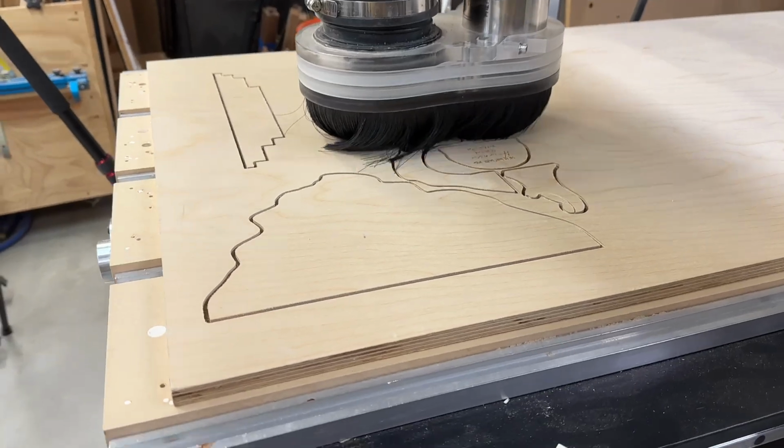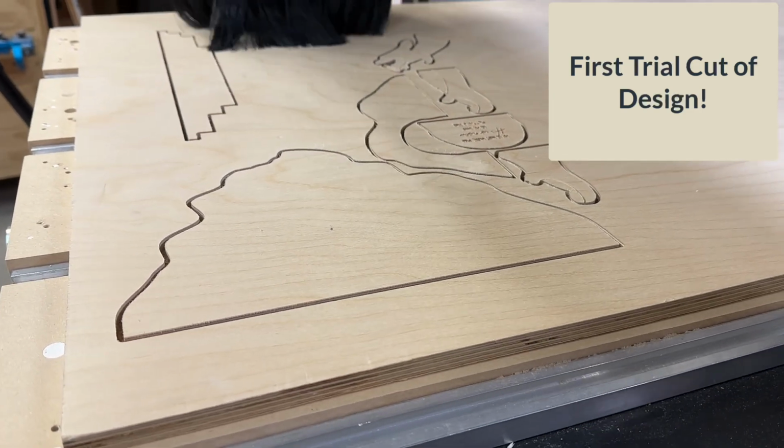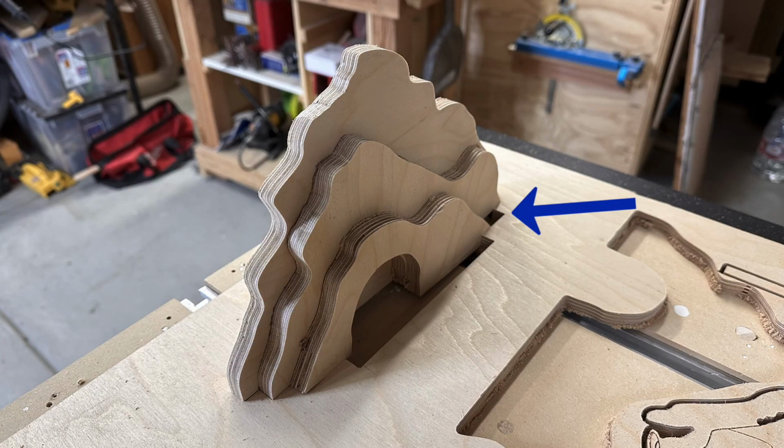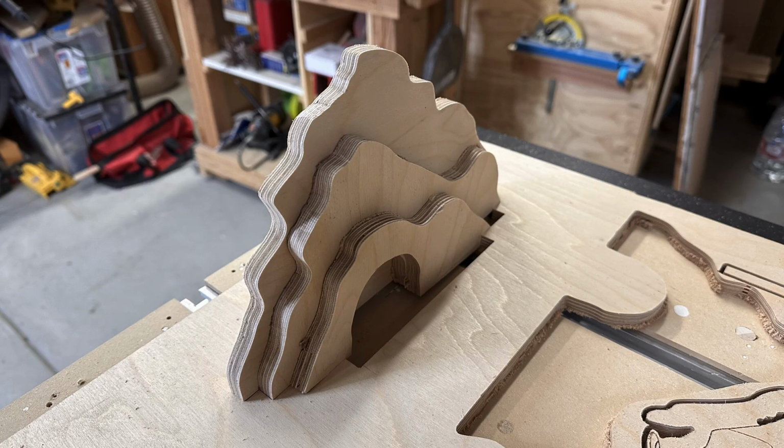We went ahead and did our first trial cut of pieces, and afterwards we did a test fit in the slots, and we noticed that they were a little loose and the slot had slid over a little bit. So we went back into VCarve Pro and made some adjustments and started a second trial cut.